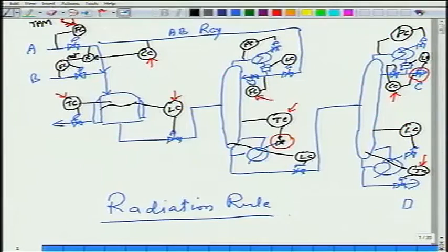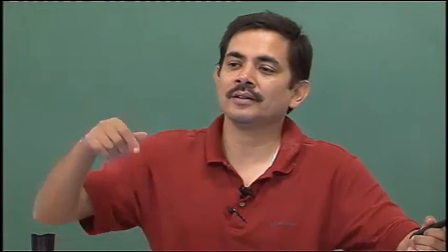The point is, this throughput manipulator may be 100, 150, 200. The way I am managing the reflux and the reboil in these two columns, it is guaranteeing me good quality. Your point is well taken. You see, quality is always an active constraint. Just like I am saying there is a bottleneck constraint, level should be max, temperature should be max, column 1 should be at flooding, column 2 should be at flooding. I am saying these are my constraints. Quality is also a constraint, right? And please notice the way I have put in the loops, that is guaranteeing quality is maintained.